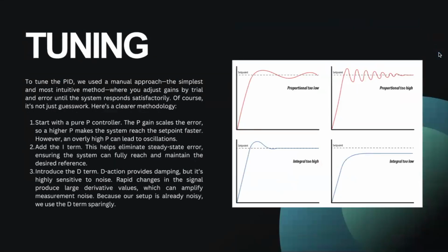Okay, so for the fine-tuning of the PID control, we use a manual heuristic-like approach. We simply made, by trial and error, little adjustments in different orders to our P, I, and D gains. So first, we start with the proportional gain. We start with this since it scales the error as well as the signal towards the desired outcome. Whenever we went over the necessary P gain, the error was overly scaled, and it led to major oscillations.